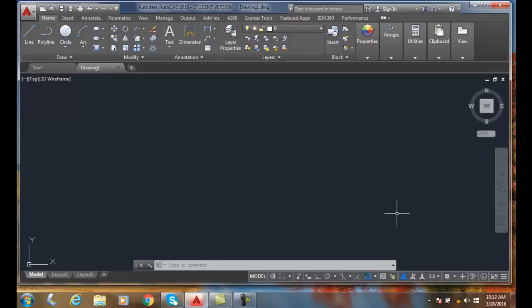An architectural dimension style might use an aligned dimension format, and it might use a text style such as sans serif or Styles BT or Country Blueprint or City Blueprint. It will place the text above the dimension line, and it'll terminate our dimension lines with architectural tick lines.